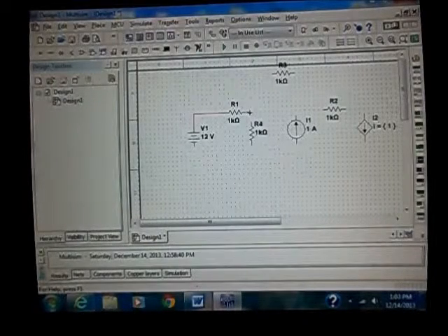So here to here, and now I cannot continue a wire here. I have to go over to a dangling node, let up, click, and that guarantees the bend goes where I want it.